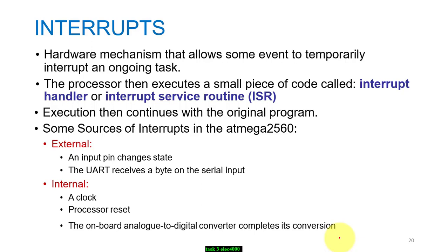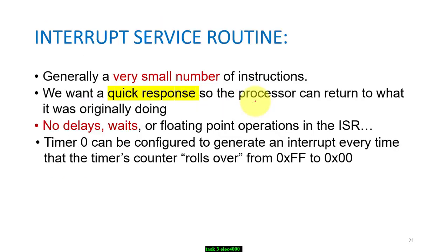The interrupts are serviced using an interrupt service routine, or ISR. We are going to call them ISR. The interrupt service routine is generally very small, with a quick response, and no delay or wait in it. Timer 0 can be configured to generate an interrupt every time it counts from 0 to FF, or to maximum.